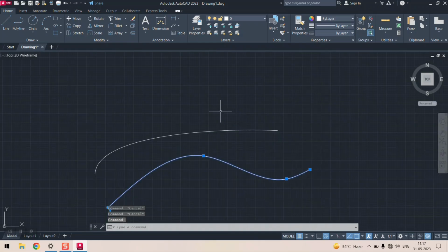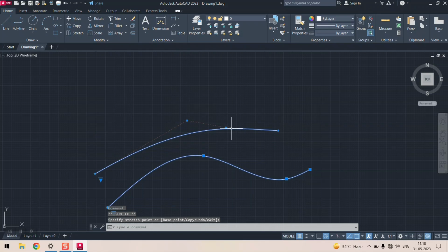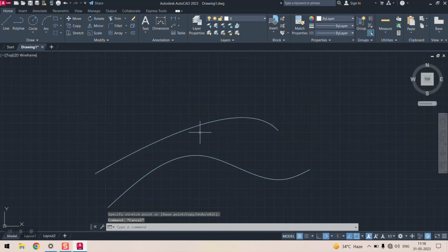Okay. So you can control this spline with the help of this option, which will give you the freedom to control the vertices. With the help of control vertices you can control your spline, but in this command you won't get that flexibility. You will get the flexibility only at the point, only at the nodes. With the help of the nodes you can control your spline operation.